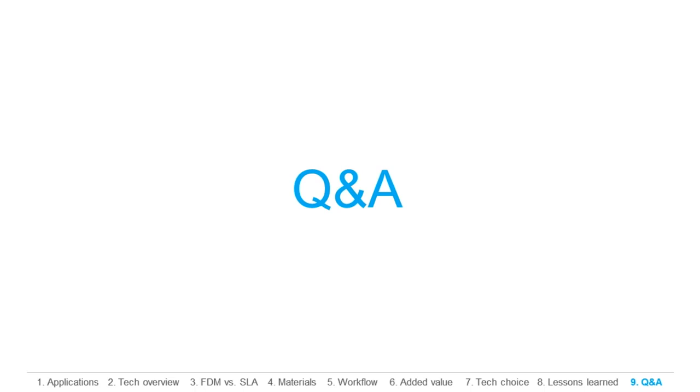Well, sure. I'll mention a few things, Chris. Thank you. The first is absolutely rotating your parts as to where they sit on the tank and build platform is a great way to extend the life. We actually have a heat map feature, so you can track where prints have been placed on your tank and your build platform, and make sure you're putting those into new locations.